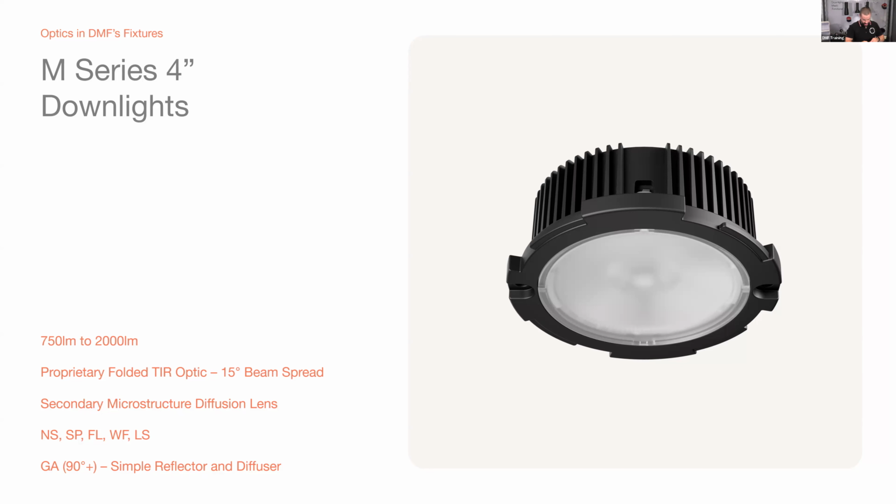When you turn that on, you get a very tight pool of light. It's collimating most of those light rays and bringing it down to this beam here. As you can see, however, this beam does not have a lot of uniformity to it. We have rings and color fringing that come into there. So we have, in addition, a set of microstructure films that go over the top of that.